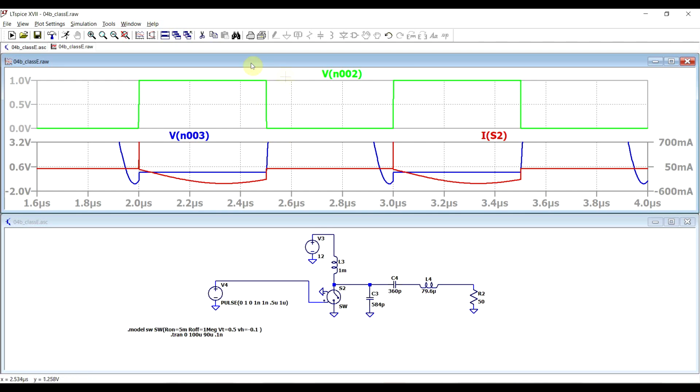And for the turning off phase, well, we do have non-zero current, so we do have losses associated with this. However, this current is not really the peak current. It's some value lower than that. So because of this operating mode, this type of amplifier can be designed to be extremely efficient. So switching related losses will be highly minimized with this type of operating mode.